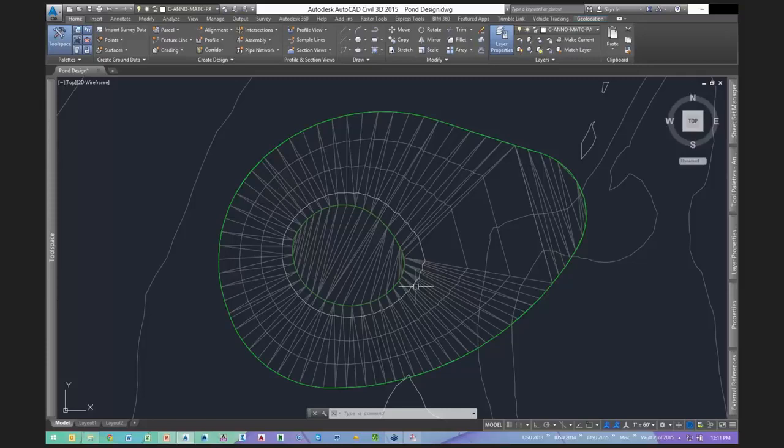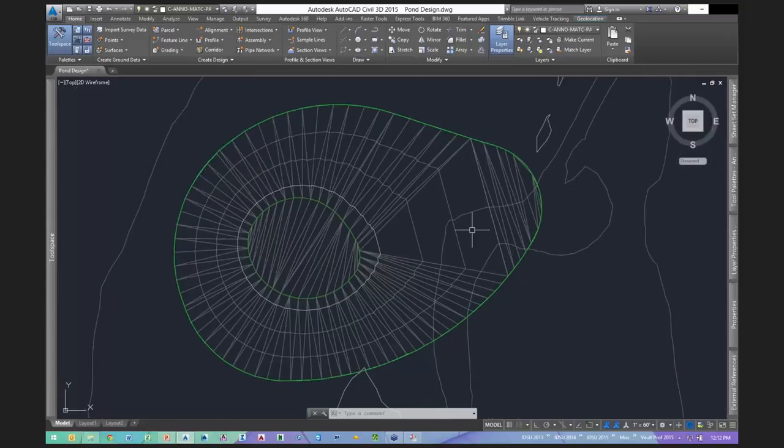But when you get over here, they're not so concentric or parallel anymore, and the TIN doesn't really know what to do. What we may want is for TIN lines to be going from here right up to there, but instead they're just crossing right here, and we've got a flat spot up here. So how do you control that? Well, you could swap edge 50 times and clean that stuff up. The better, more dynamic way to handle it is to put in a couple other break lines.